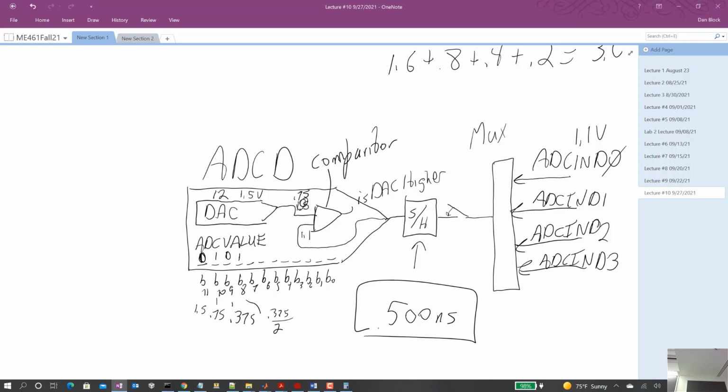We want the most current sample. So, we tell it to sample, we go off and do other things, or we have the PWM telling it when to sample, however we're doing it. But then we know things are done when the ADC interrupt is called, and then we read the results registers inside there. Okay. So, anyway, we've got 3 minutes.